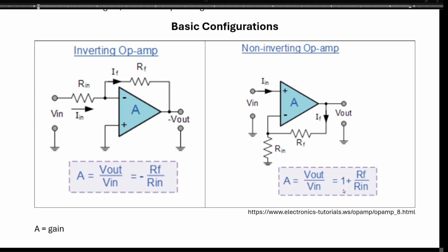So the gain is equal to, here's the formula, 1 plus RF divided by Rin, and that's going to give us the gain. The gain helps us with calculating the output. If the calculated gain is going to be 2, then 1 volt times the gain of 2 gives us 2 with no negative sign. It's just positive 2 because it's a non-inverting input, right?